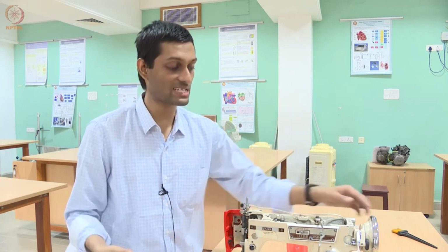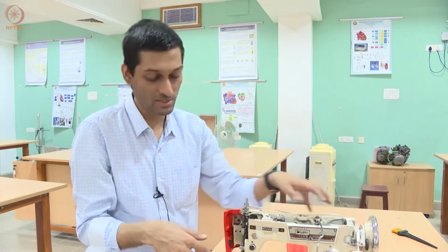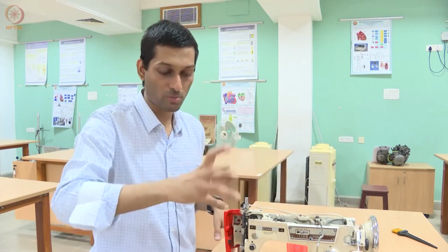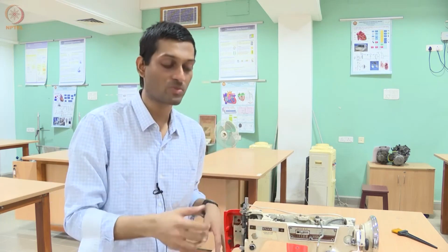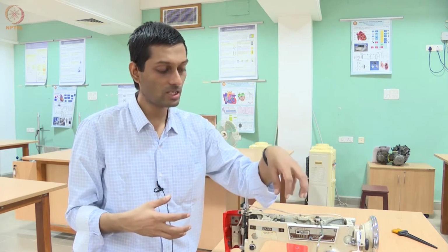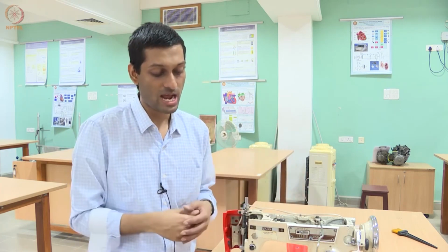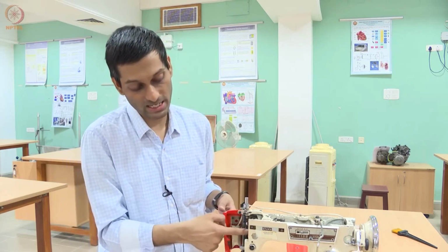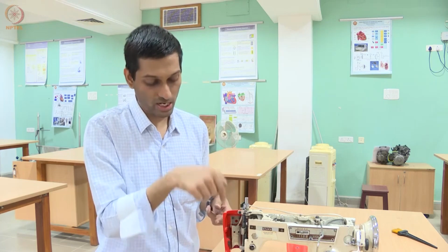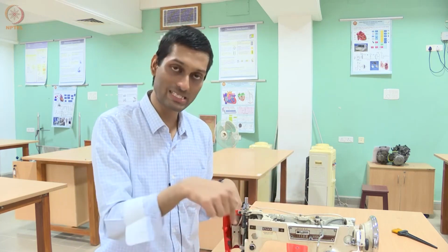Where all did we see a crank slider? We saw the crank slider mechanism that goes from the top part of the machine and powers the bottom spool to oscillate the bottom part of the machinery. And we saw cams that power the zigzag stitching of the mechanism. And where else did we see a crank slider? We saw a crank slider here that drives the needle up and down. And then we saw a cam mechanism that helps in giving you a zigzag stitch.